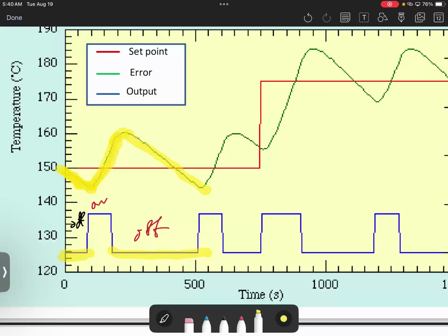You can imagine, again, assume that you want to walk from here to, for example, Bayruni. Do you prefer to walk or do you prefer to run, then relax? Run, relax. What do you think? Walk, of course. So walking, you will reach faster, right? The same thing applies to the controllers. If you turn it on, turn it off, turn it on, turn it off, this will consume a lot of fuel. In some applications this might not be sufficient. Here in the temperature, it can be okay, but it will not save energy.